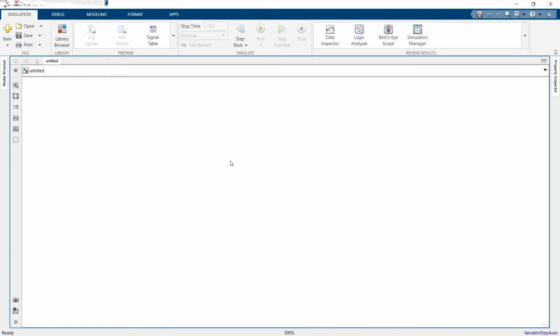Source cutoff IGBT. So source cutoff means this is used to cut the source, this voltage source. And I also require a load cutoff IGBT. I'll just copy and paste it for reuse. Let me flip this block. So I'll go to the format, flip block, I'll flip it left right for proper connection. Now this is my load cutoff IGBT.